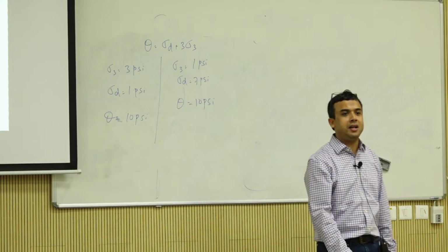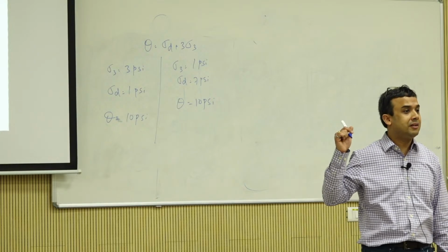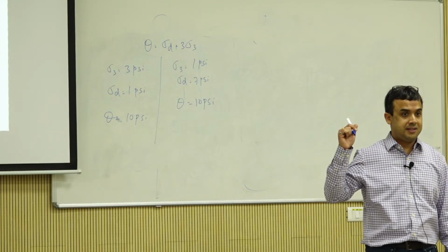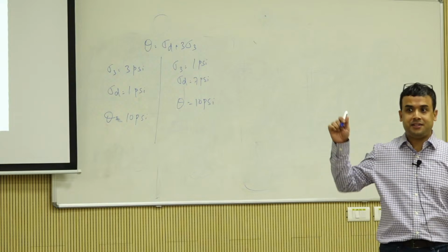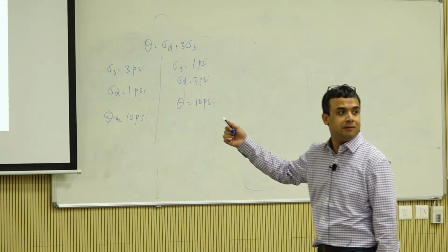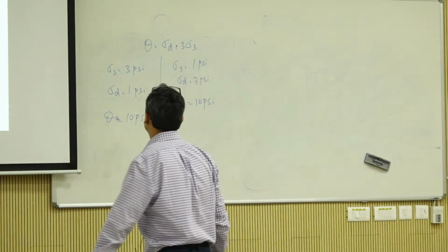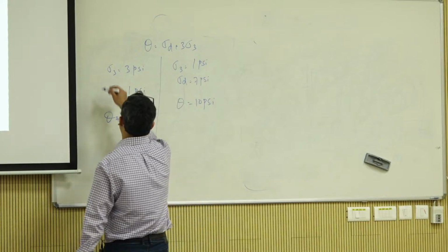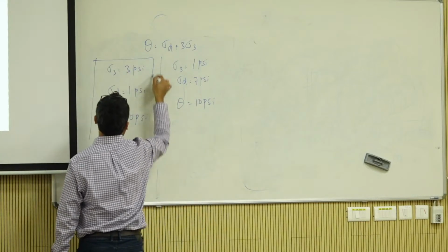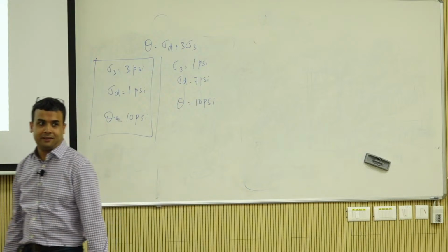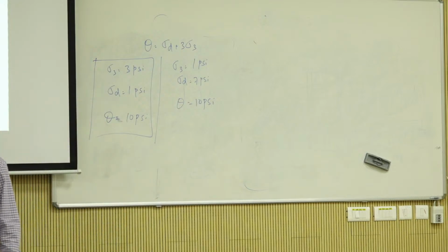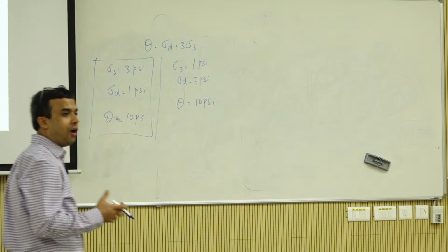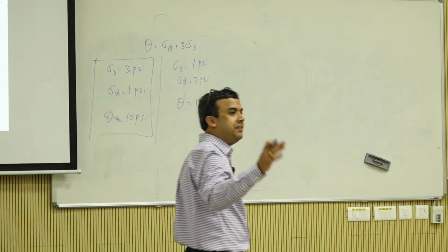In the k theta model, the modulus value is the same. Is the material going to behave the same? Which one is it going to be stronger? Much more confined, right? So in the k theta model, you are not able to isolate between the effects of confining and deviatoric effects.